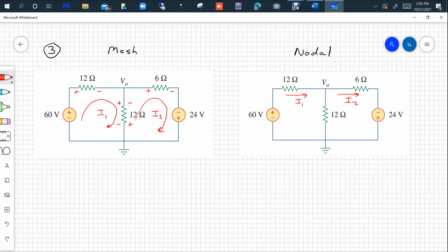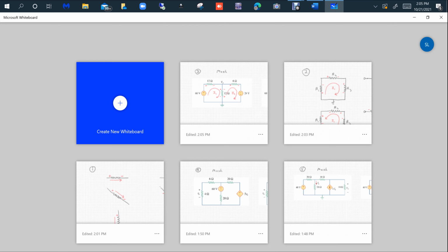Well, as soon as you draw an I1, put a plus to minus. As soon as you draw the I2 arrow, put a plus to minus. And let's say usually you have that going to ground, I3. Put a plus there and put a minus there. Before you start the problem, you have to put that in. You could assign currents in different directions. It'll come out in the wash as long as you put the passive sign convention in. The importance of that, maybe I'll show you on the last slide for those of you that had nodal and mesh analysis. Let's go to the fourth.